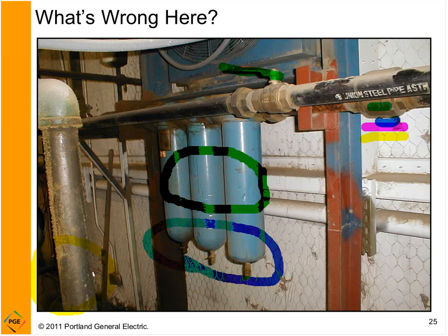Well, this plant said, well, we got a filter in here, and we're still getting dirty air downstream, so we're going to put more filters in. On the previous slide, we talked about pressure drops. One source of pressure drop is multiple filters, because you can't clean unless there's a pressure drop. I mean, it's almost part of the definition. You have to go through a membrane, a cyclonic effect. Something has to happen to clean the air, and one of the outcomes is a pressure drop.